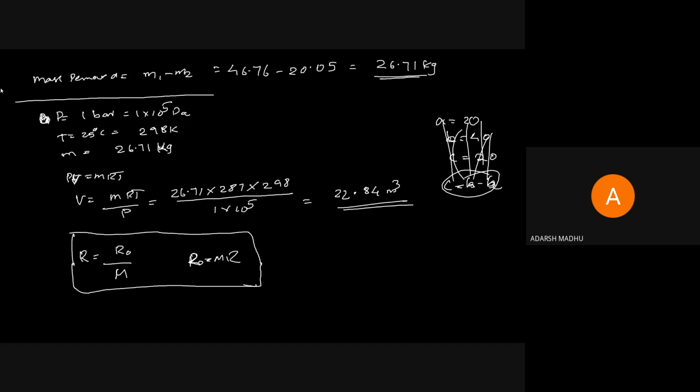So there is a value for carbon dioxide. If a question is asking like that, and if A and B are given in your problem, you can do the problem. If not given, you cannot take that value from your steam table. It is not in your steam table. It is a different diagram. I will give you the particular diagram and the problem related to real gas through the PDF. I think the question will not be asked because the table is not in the steam table, and if the values of A and B are not given in a question, you cannot find out the value from anywhere. So we are not doing the particular problem. We are only doing the ideal gas problem.